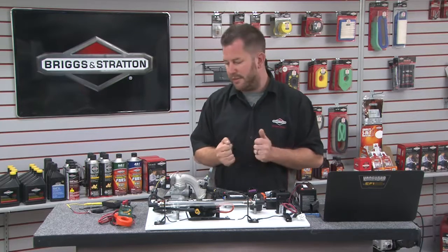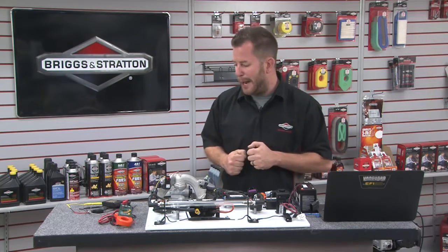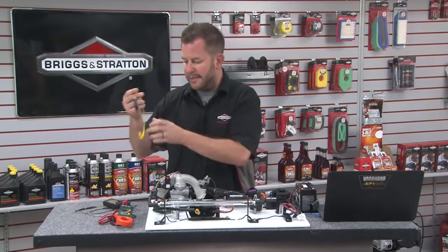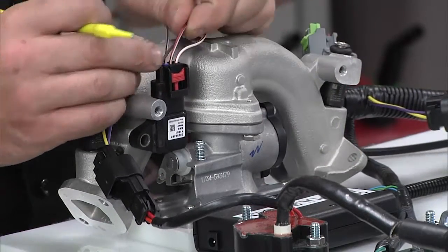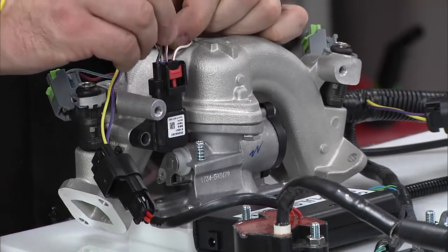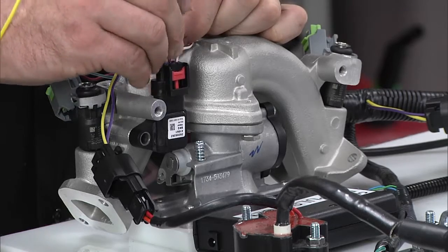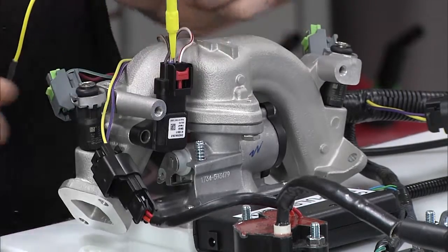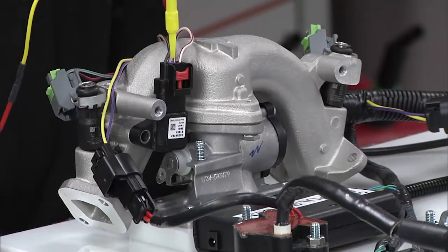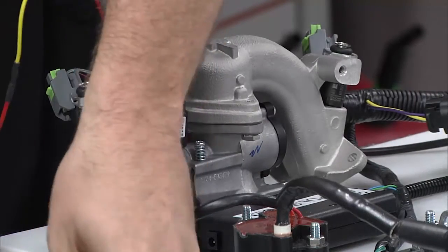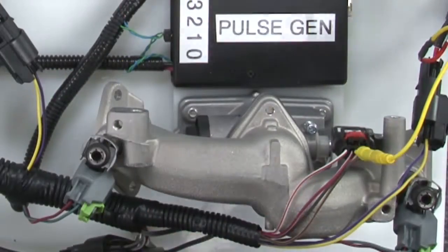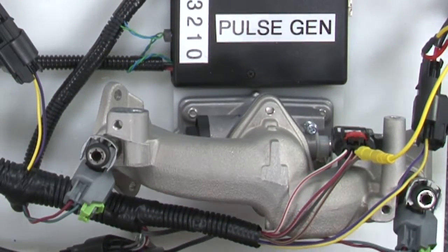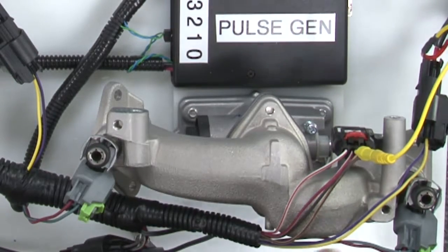So first things first here is we got to take some measurements using the back probe pins and a voltmeter at the sensor itself. So first thing I'm going to do here is I'm going to take my red wire with a white stripe right here. I'm going to back probe that one, and then I'm going to hook that alligator clip up to my red meter lead. That way I can begin a test here of testing our 5 volt reference circuit right up front. Now, it's probably working okay, seeing as it produced the code for us, but we want to always verify.